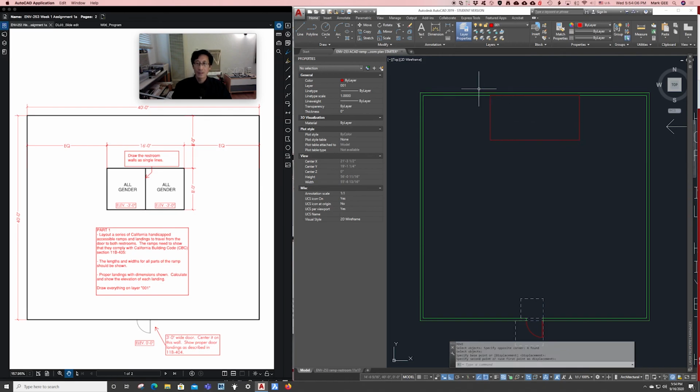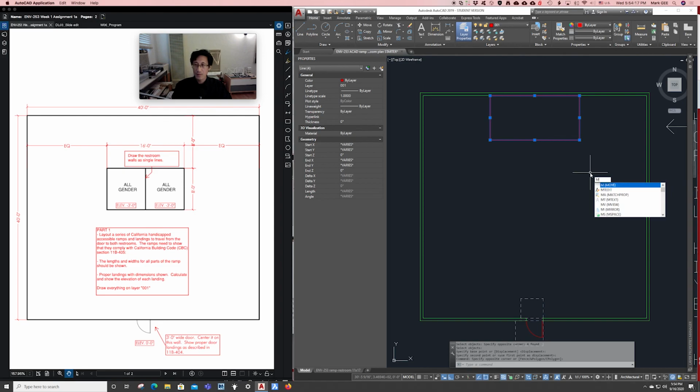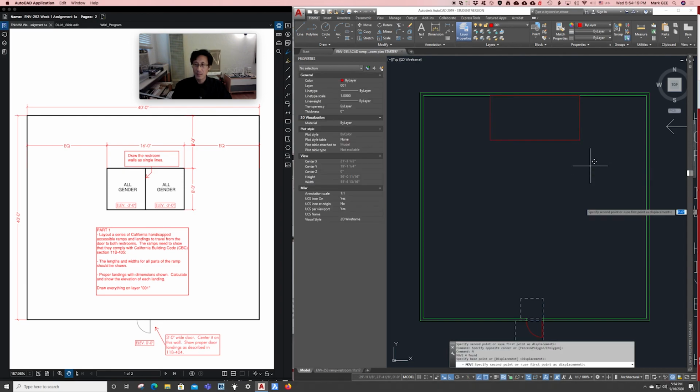All right. Now let's move the 8 feet from here down in plan, south direction. I'll select these, pre-pick, do the move command, click anywhere, move the mouse in the direction I want. I'll just enter 96 for 96 inches, enter, and there it is. So the outline of our restrooms is positioned correctly.